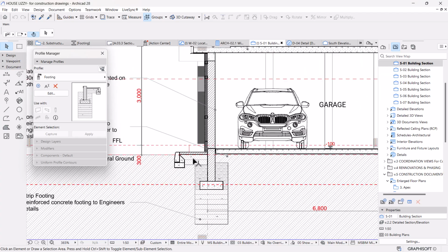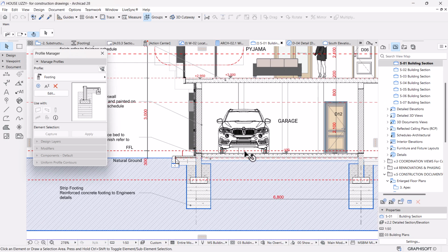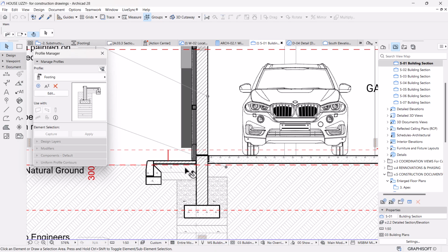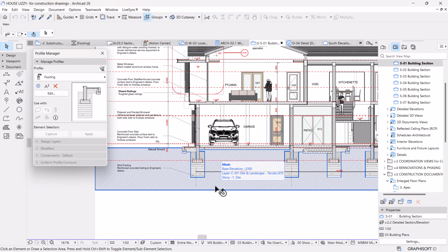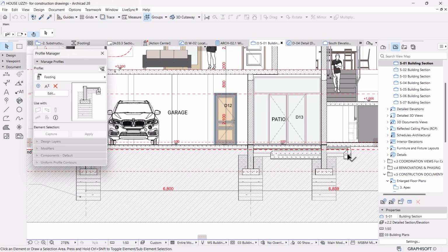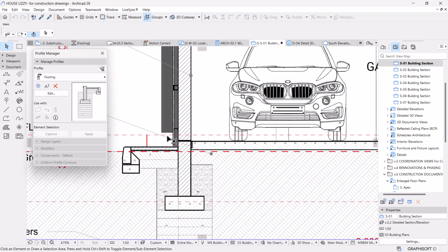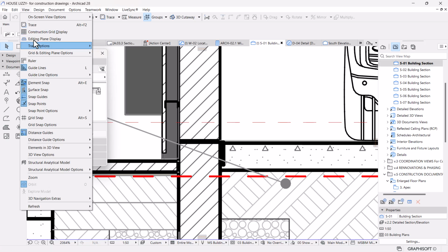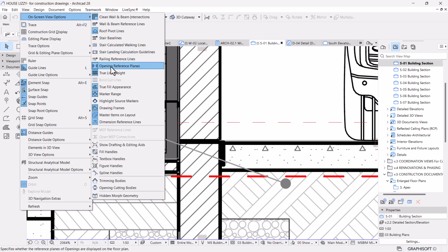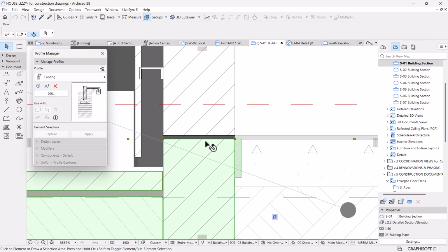Yeah, especially on this side. Okay, so one thing that I need to check is the joints. I'm gonna go to view, then unactivate the true line so that I can see the joints.